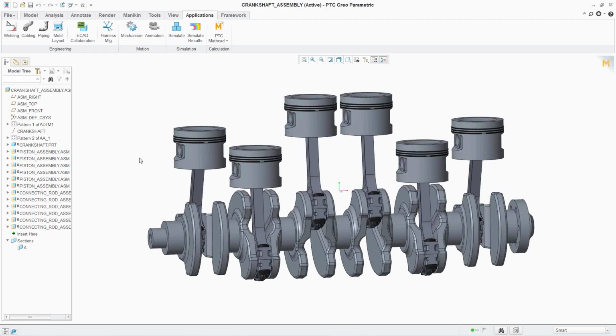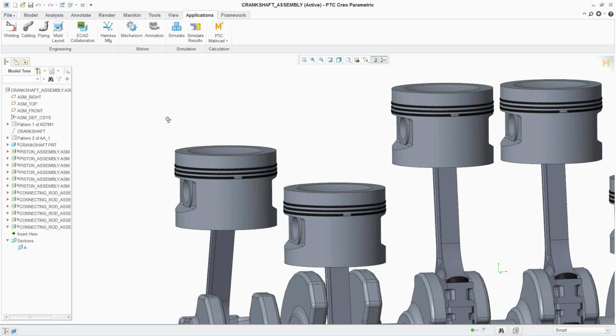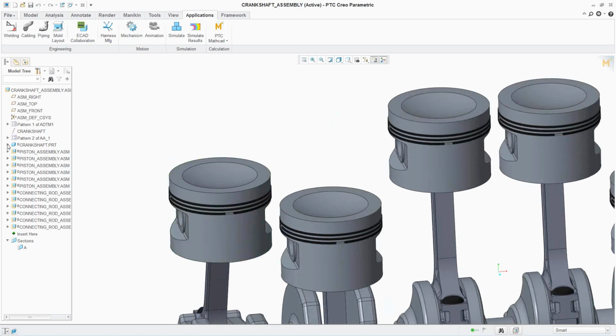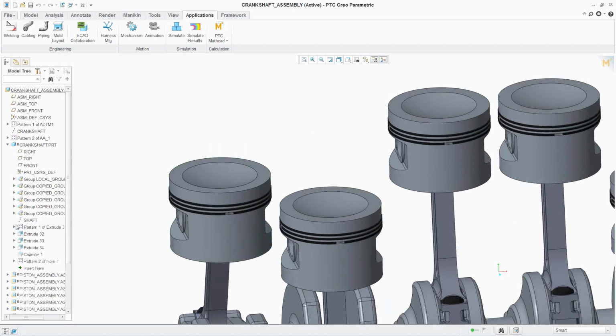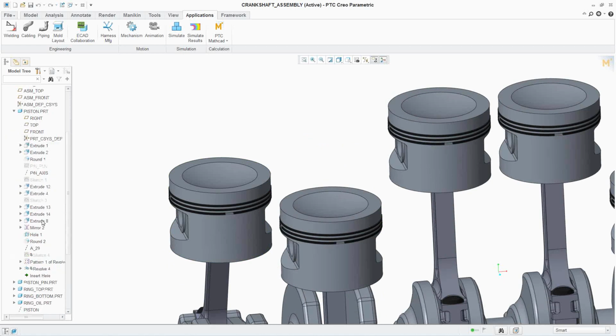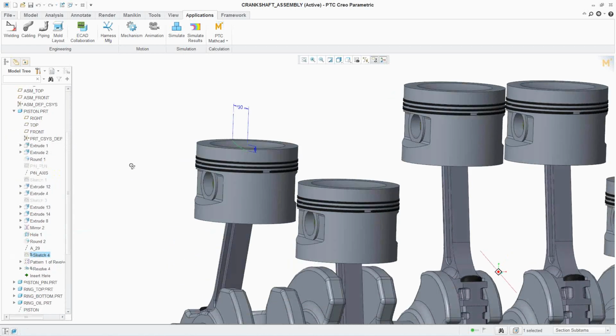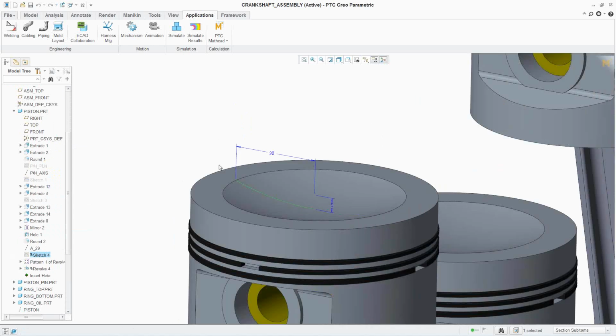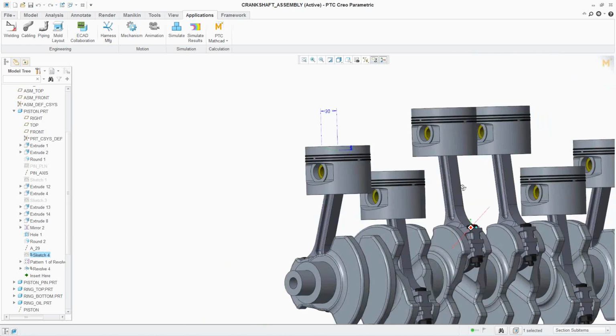And then back in Creo, we'll do a bit of an optimization on the surface of this piston head. If I come into the piston assembly and see the definition of this sketch, you can see there's two values typed in there. There's a little spherical indentation. So we'll do an optimization around the surface area and the volume of that little cap there. And I'll tell you why that's important in a second.